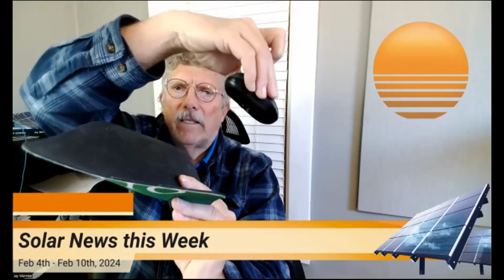All right, so if this is the solar panel here, and the panel is angled for the equinox, this would be based on latitude. So if I'm at 40 degrees north latitude, the angle would be 40 degrees. On March 21st and September 21st, we would have a 90-degree angle between the panel and the sun. But in the winter, the sun would be more down here. In the summer, the sun would be more up here. And the angles would not be at a pure 90 degrees.